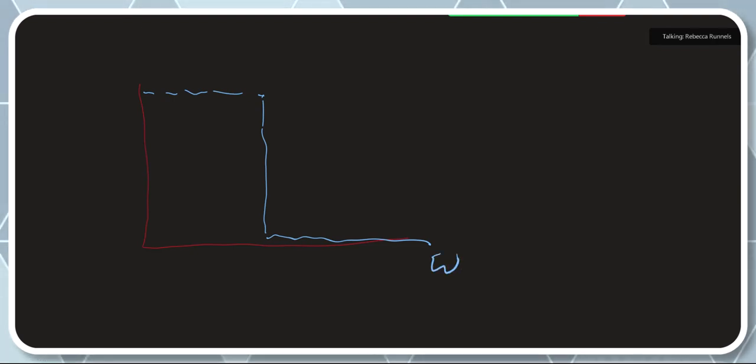So what a filter does is it allows you to get just some part of the signal. It filters out parts of the signal. So the ideal low pass filter looks like this. This is frequency down here, that's angular frequency, and this is the magnitude of your transfer function, the magnitude of your response.